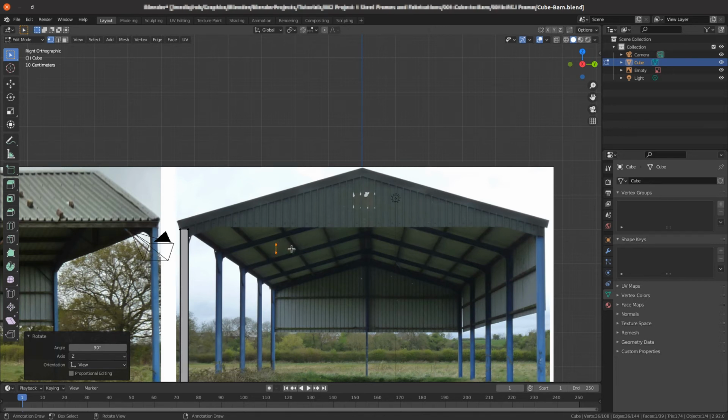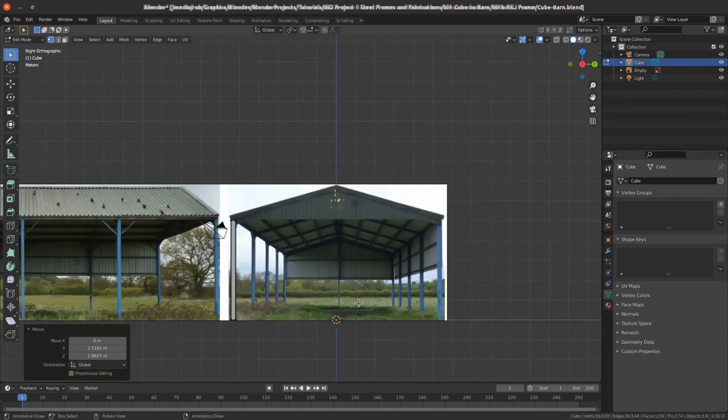So if we grab and position it somewhere just below the flashing, we need to get it exactly on the XY0 axis where the Z-axis indicator lies. And one of the ways we can do that is to scale it to the 3D cursor. Because the 3D cursor is sitting exactly on the world origin, we can move this across to where the world origin lies.